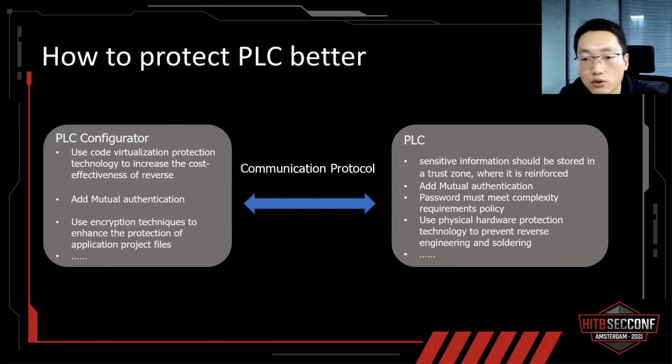The second is to introduce the idea of mutual authentication, so that the PLC and the configuration software are verified mutually. The third is to use encryption technology to strengthen the protection of protocol fields, because sometimes protocol fields are an attack vector that we often overlook. With protocol fields, one can obtain the password information, which can be used to bypass password protection like we showed in the above